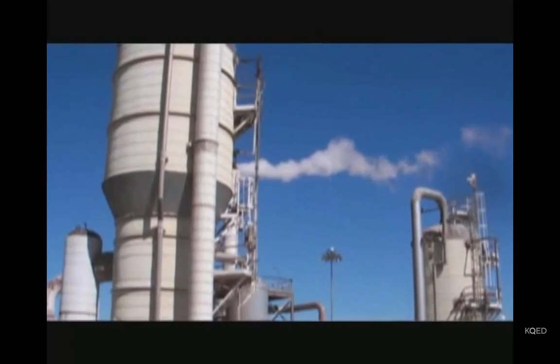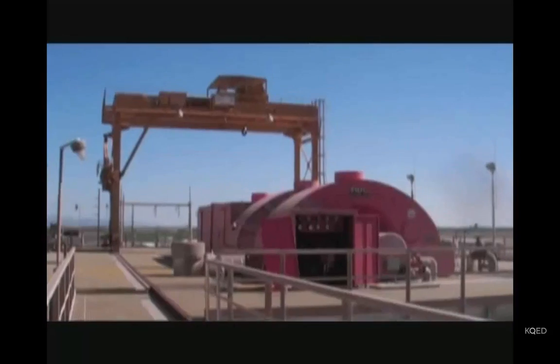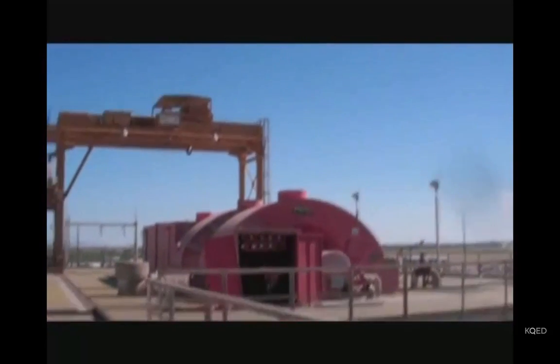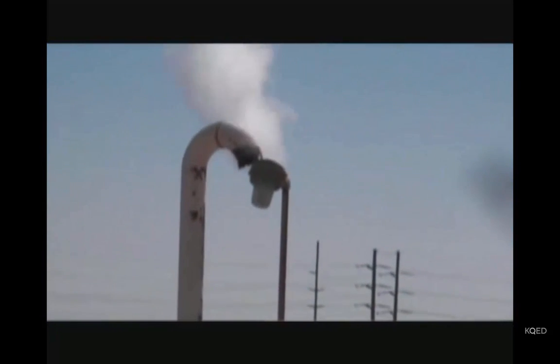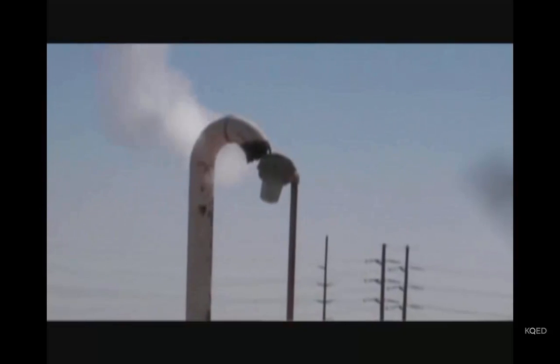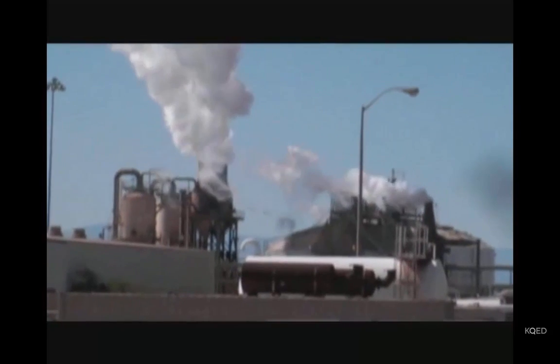And so that hot water comes up through our wells, which are about a mile down in the ground. We take that hot water and we extract the steam by depressurizing it. The steam is run through a turbine which generates electricity, and that's put on the line. Then the hot water that's left over from that process we clean out and re-inject back into the ground to renew the resource and be able to use it again.